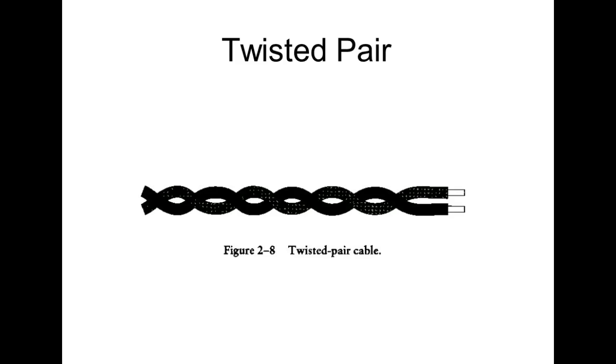What happens on this is we do exactly the same thing. When we roll a twist, we set up an inductor. The spacing between the two inside conductors sets up a capacitor, so that adds an impedance to this cable. This is why when you splice or terminate this stuff, you cannot untwist that cable just to make it convenient for you. In fact, the maximum untwist is a quarter inch. You see people run that, and if you untwist it, you've changed the characteristics of the cable, which means it won't run as fast.